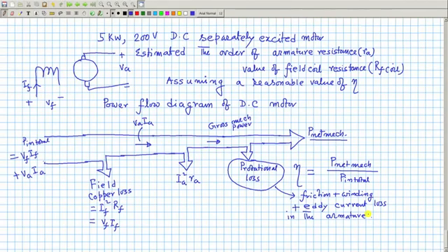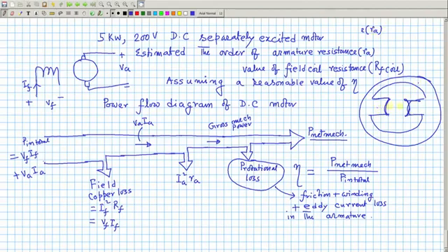See, in the case of a DC machine, all currents are DC, is it not, and that is why the field poles and the yoke structure are made of solid iron. Generally, in small machines, it is just a solid structure. This is the yoke, these are the poles, this is the stator part, made of solid iron, and here is the armature.